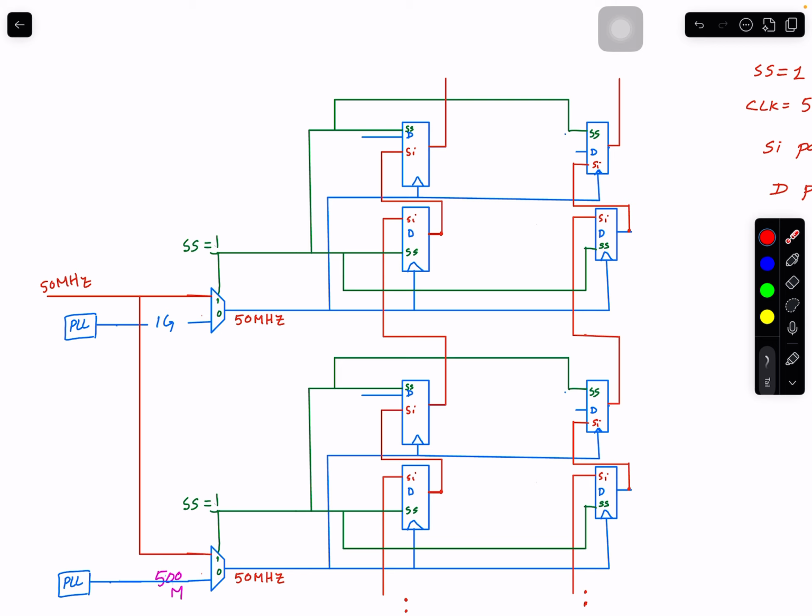In that case, first of all, I need to make sure the signal coming from these is connected to each other too. The scan select, when it is 1, is selecting the red clock, and with 0 selecting the other clock. So if I put the scan select mode and do set case analysis of this port equal to 1, only this clock will be valid in your design.